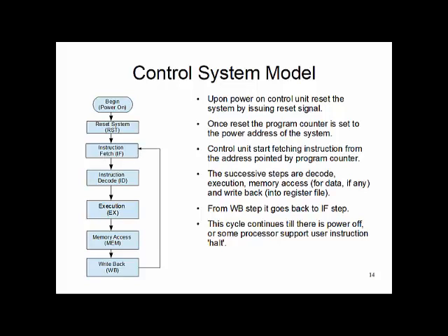So it will first fetch that instruction, decode and register fetch, then execute, then go into the memory access and then write back the result. So each assembly instruction or machine code is associated with 5 cycles. Okay, so we'll be developing a 5 cycle processor like this, which always follows exactly these steps.